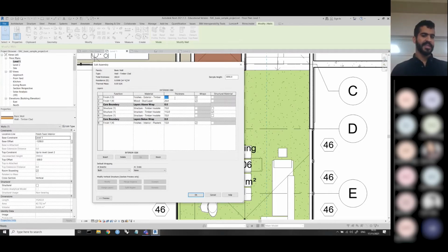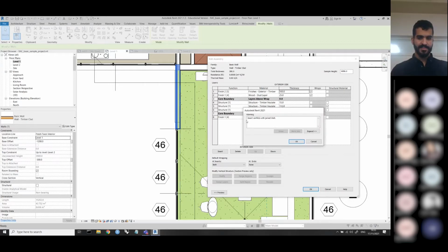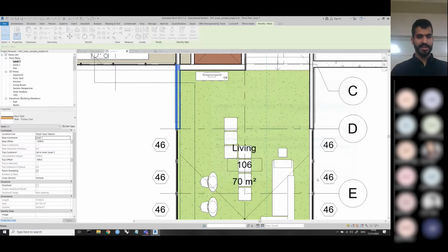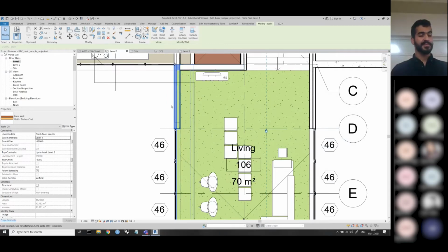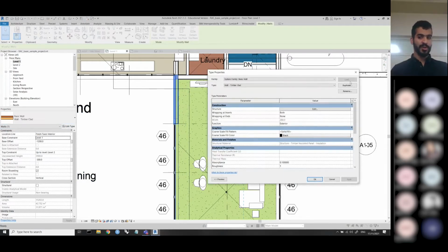We see a thickness here. If I come here, I'll change the thickness to 100. I want you to see how it is now. And I click on OK. There's conflicts, fine. This is why Revit is not a design software, because I'm going to ruin the whole model now. Click on OK. You see how it increased thickness? This increased thickness for the type, for the family. So if I'm going to create a new wall, what I'll do here is duplicate and call it my wall.